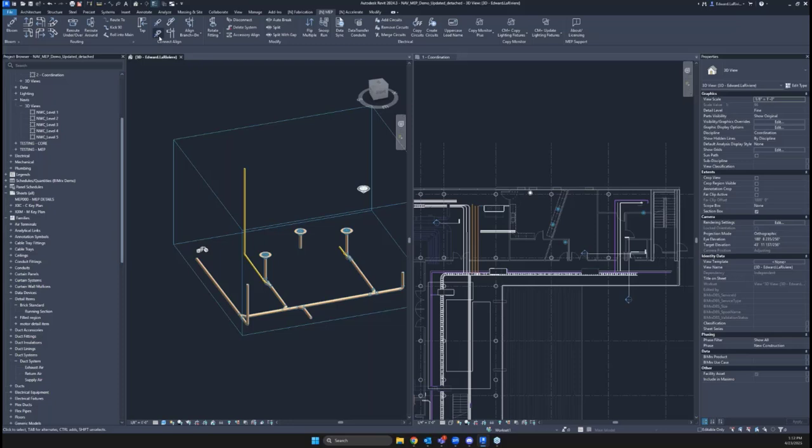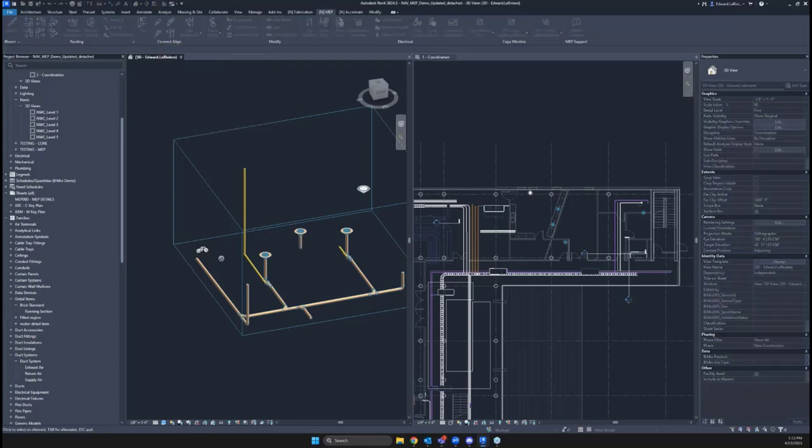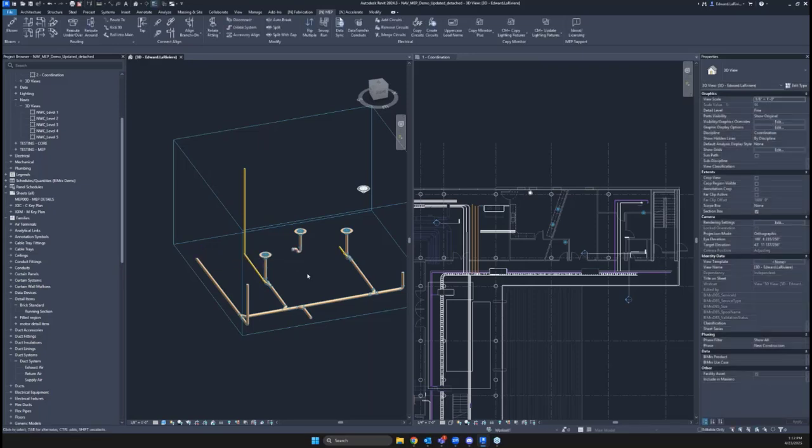Let's introduce another new tool called Move Connect Align, which is going to let me take that vertical and automatically rotate, move, and connect that P-trap. I don't know why every P-trap was built sideways. Someone made a decision back in 2013 or so, and we live with it. So there's a button that makes you not have to live with it anymore. Just move, connect, and align it.